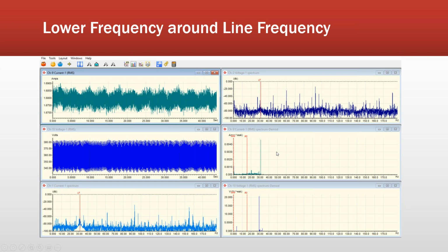And I tell vibration analysts, the difference with electrical signature analysis is like standing on your head and crossing your eyes or drinking heavily. You've got peak pairs of everything, and you're measuring from the top down versus the bottom up for vibration. So I will have, say, my peak at line frequency, say here, this is a motor.